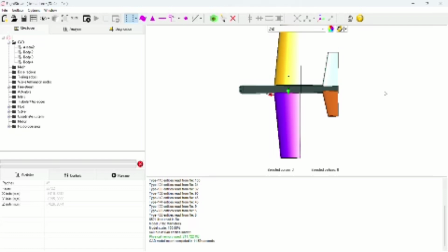Completely, we'll have 4 wings and 1 fuselage, such that we can apply boundary conditions such as trailing edges only to the wings rather than to the fuselage, and we'll keep the base regions only for the fuselage. So that is the main reason why we separate it.